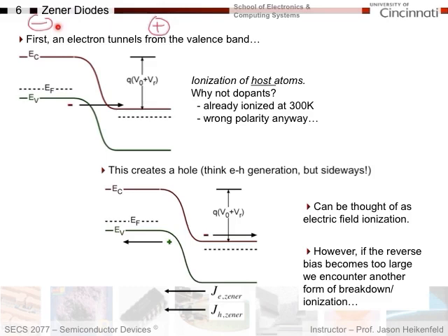Well, what can happen is, remember, the valence band is just a bunch of silicon atoms, right? And so anytime we get an electron lifted from the valence band up to the conduction band, it leaves behind a positively charged hole. Well, if that process can occur across this barrier in this direction, if we make D small enough, I can have an electron leave a silicon atom in the valence band and get to the conduction band over here, which is an easier route than going this way. And so my electron leaves a silicon atom in the valence band, moves over here, and again, we call it valence band because that's where the valence electrons of the silicon are that are available for this.